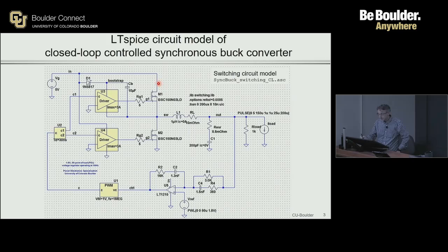We can recognize the synchronous buck converter, where we have 2 power semiconductor MOSFETs switched in a complementary manner. Then there is an LC filter. The circuit model does include the series resistance of the inductor L1, and it also includes the ESR resistance of the capacitor. In fact, the values in this example are the same values that we used in the review lectures last week to illustrate the notions of averaging, small signal modeling and transfer functions. Basically the same numerical values.